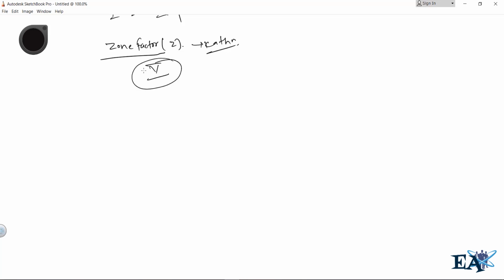So zone 5 is the highly seismically active zone, a high seismic zone, and great care needs to be taken while designing a seismic resistant building in this area. The value for Z for Nepal is 0.36.